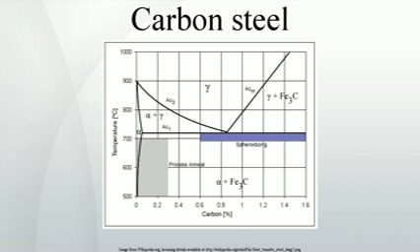Types. Carbon steel is broken down into 4 classes based on carbon content. Mild and low carbon steel. Mild steel, also known as plain carbon steel, is the most common form of steel because its price is relatively low while it provides material properties that are acceptable for many applications, more so than iron.